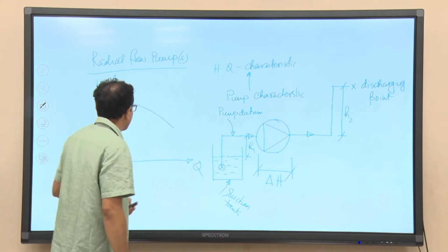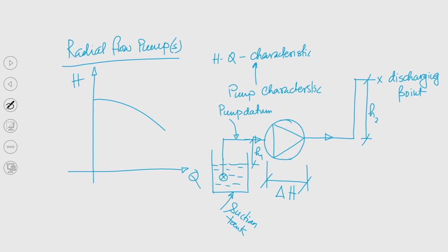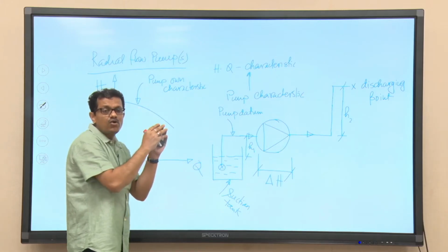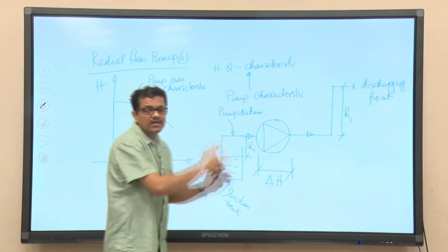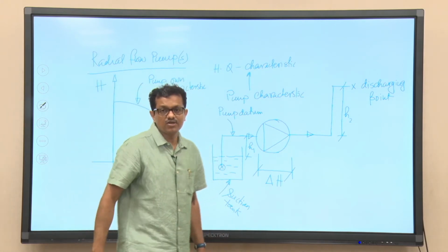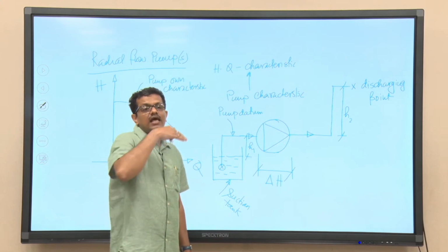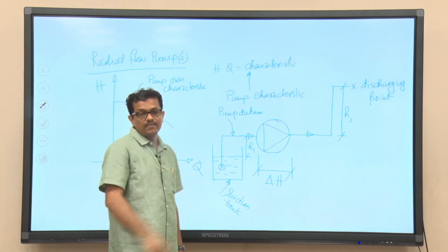So, if we try to recall, I did not draw anything. So, this is the pump's own characteristic, let me tell you, and that will be supplied by the pump designer. But before the pump designer starts designing the pump, he or she must know about the system resistance, and that is what I have discussed, because he or she should know the NPSH available, right.